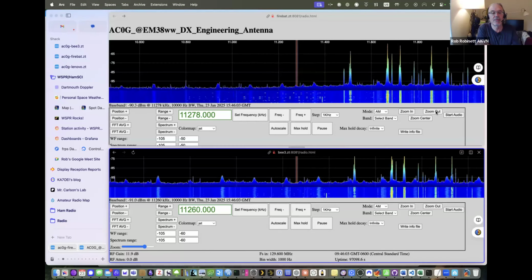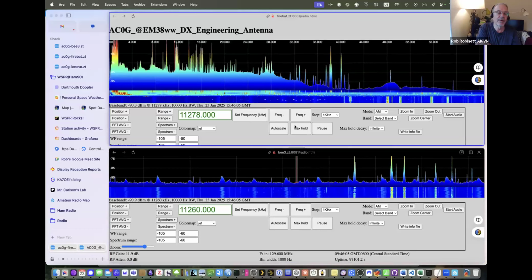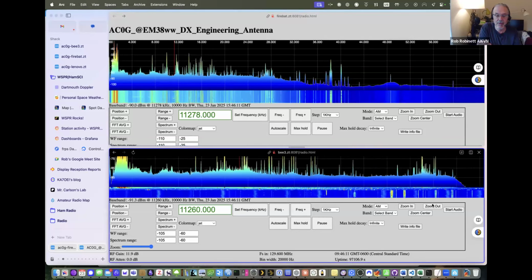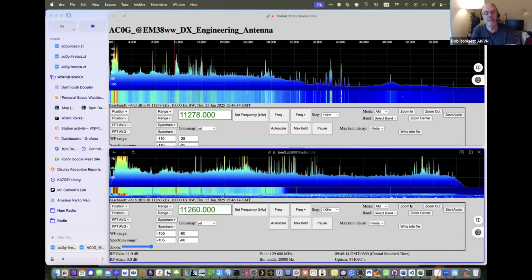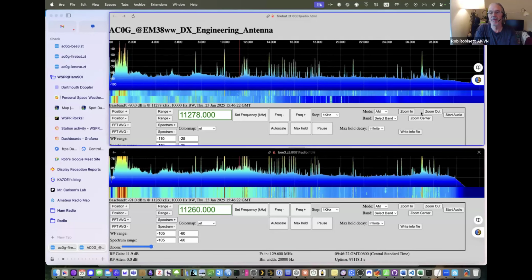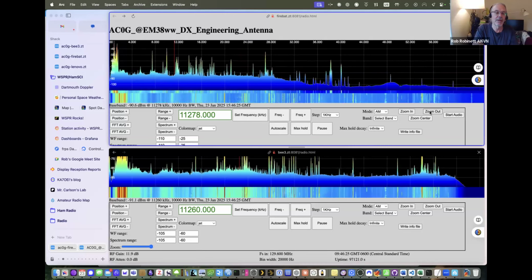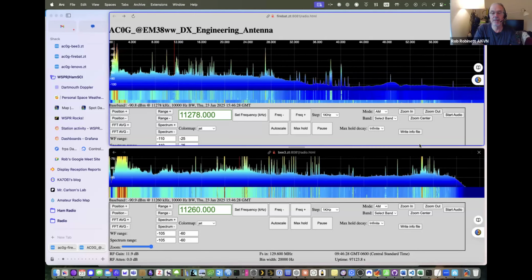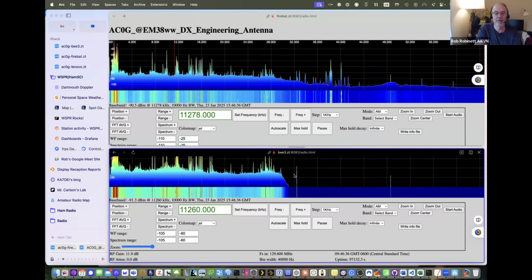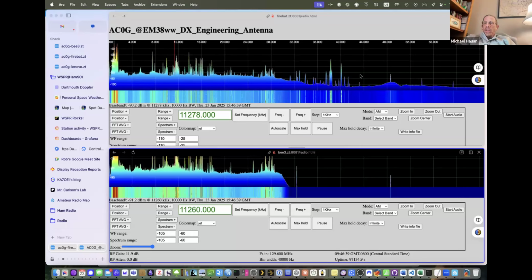I think that while these specific RFI sources may not be relevant to our measurements and recordings, maybe they're not at WWV frequencies, they demonstrate the vulnerability of these different receive systems to impairments, and since every site is likely to be different in terms of its RFI sources, trying to understand and eliminate them as much as we can helps us wherever we go, and eliminates that uncertainty and variability. I'll just point out what I've done here is I've zoomed out to 64 megahertz.